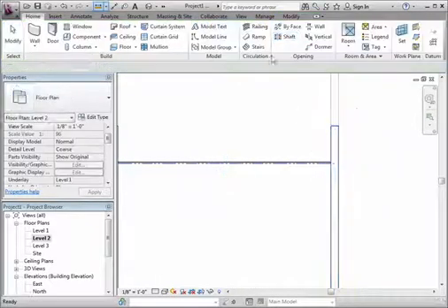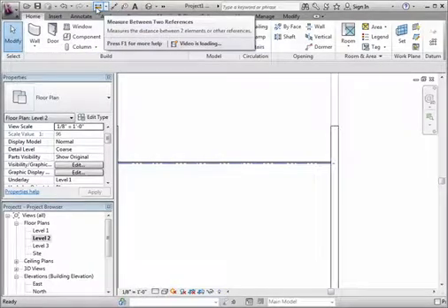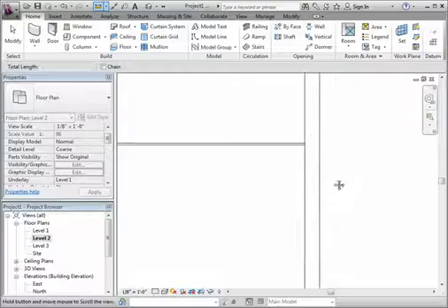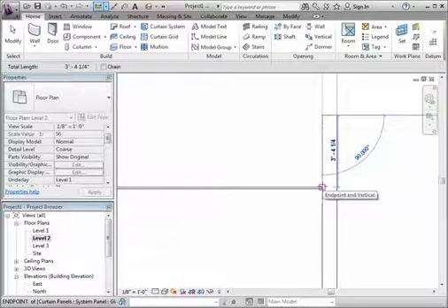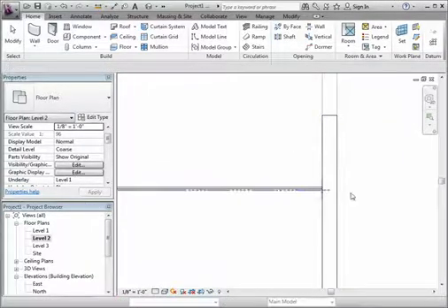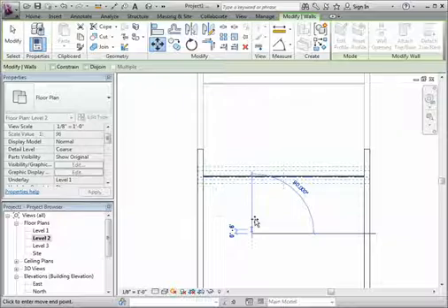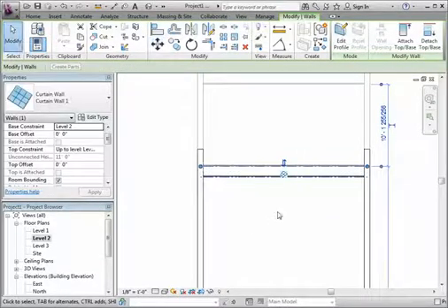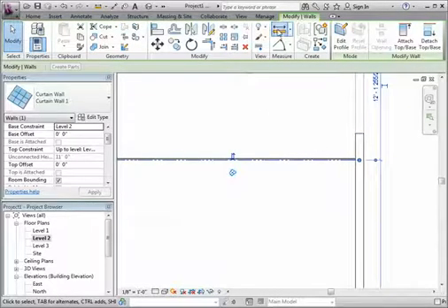One thing I can do is use this little measure tool up here. I'll go from here to here. It's 3 foot 4 1/4. I know that if I select this, I could go to the Modify tab and move this 1 foot 4.25 inches. And check that again.